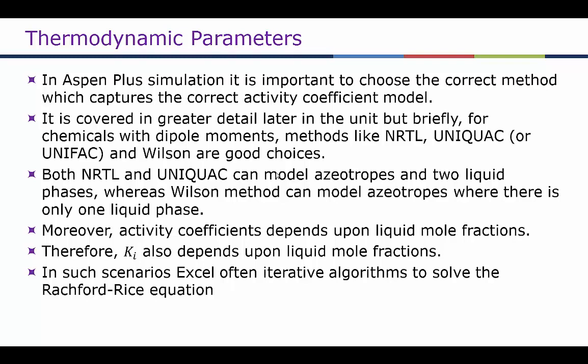So distillation type problems reach kind of an equilibrium where beyond that you cannot get separation. So azeotropes are not good when it comes to separation. Another way of thinking about azeotropes is that the partitioning coefficient will be equal to 1. Ideally, we want the partitioning coefficient to be much greater than 1.